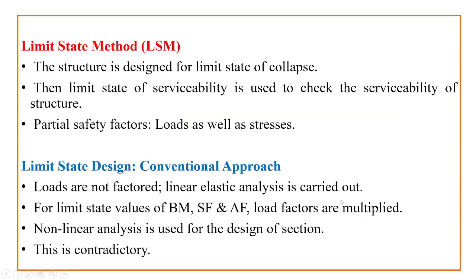Now going further, the next approach is the limit state method. We know that the structure is designed for limit state of collapse or limit state of strength. Then we apply the serviceability checks to check the serviceability of structural elements like deflection or maybe cracking or maybe from durability point of view. Now here in limit state method, partial safety factors are applied on loads as well as stresses.